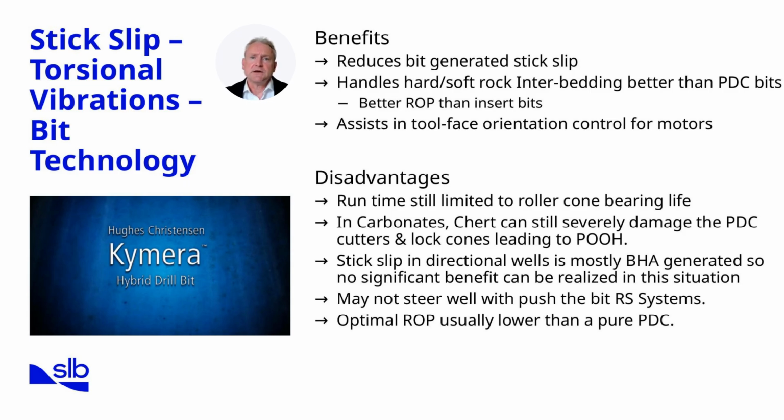Additionally, stick slip in directional wells is often BHA induced rather than bit related, meaning bit technology alone cannot always resolve the problem. Steering performance can also be compromised in push-the-bit rotary steerable systems, and optimal ROP may not match that of a pure PDC design. The key takeaway is that while bit technology offers some relief, it is not a universal solution. We must combine it with other downhole and surface strategies. With that in mind, let's now look at downhole technology for stick slip mitigation.